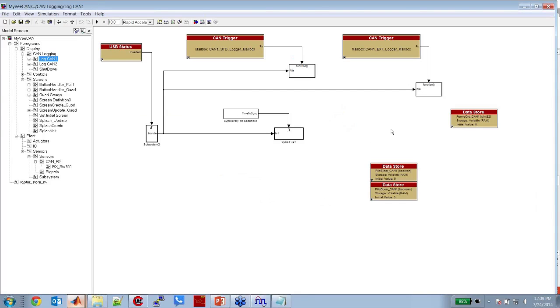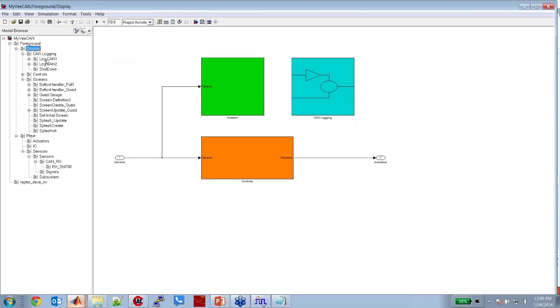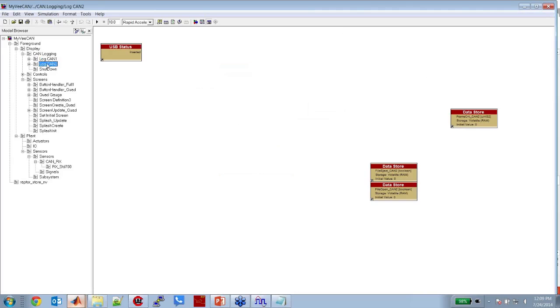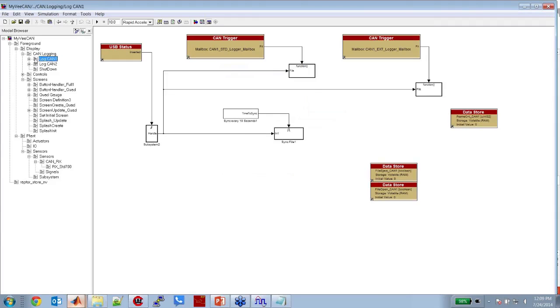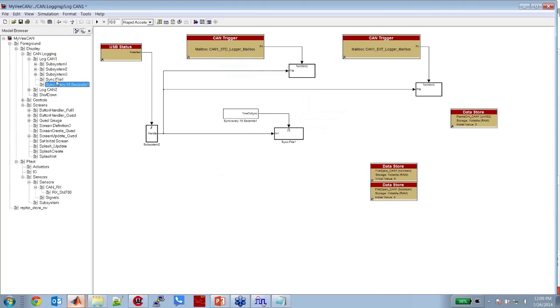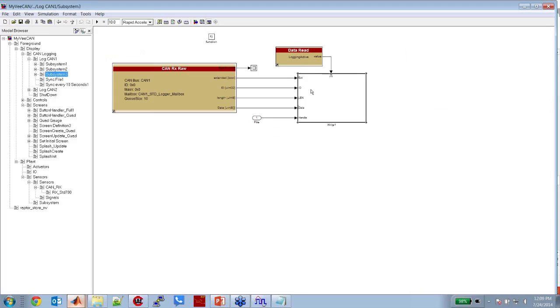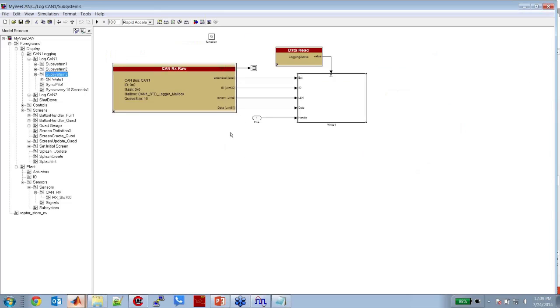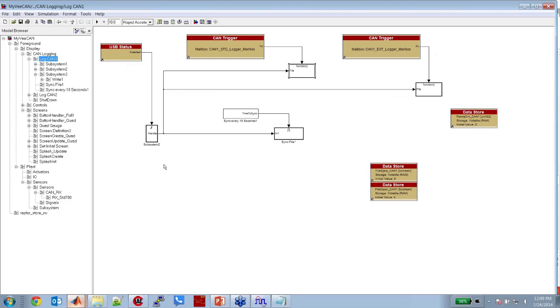And that is all. So the template project comes with a default CAN1, CAN2 logging. It logs all the CAN messages for you. If you wanted to do specific CAN logging, you could go into the CAN handlers and control how you want to handle the messages. And how do you create a template project?